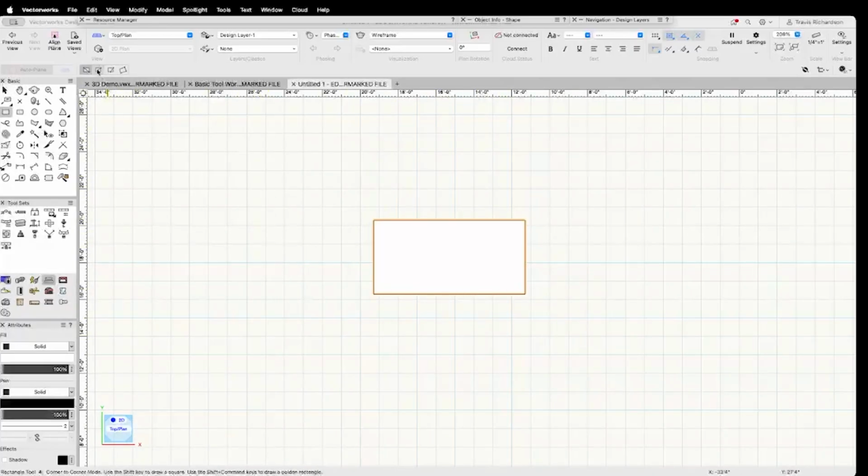Our next mode is the center to corner mode, so you're drawing from the center of the rectangle out. So with that selected, I'm going to find the top center smart point of the rectangle I just drew. I'm going to click to start the new rectangle and tab in, and I'm going to make this 1 foot wide, and let's make this 2 feet on the Y. And that'll lock that in at that dimension, and I can click to complete it, and there's my other new rectangle.